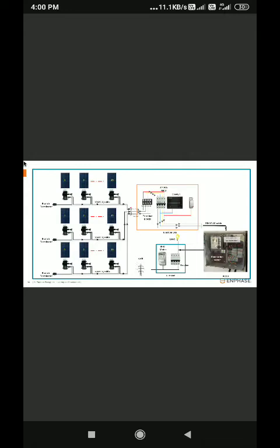Okay. So this drawing is a three-phase schematic drawing. Okay. So earlier you had a single phase. Similarly, here the number of panels will be higher in the three phase. So here, if you say I have 39 panels, so 39 times 40 is close to a 10 kilowatt or 15 kilowatt size. Okay. So you split the panels appropriately to each phase.